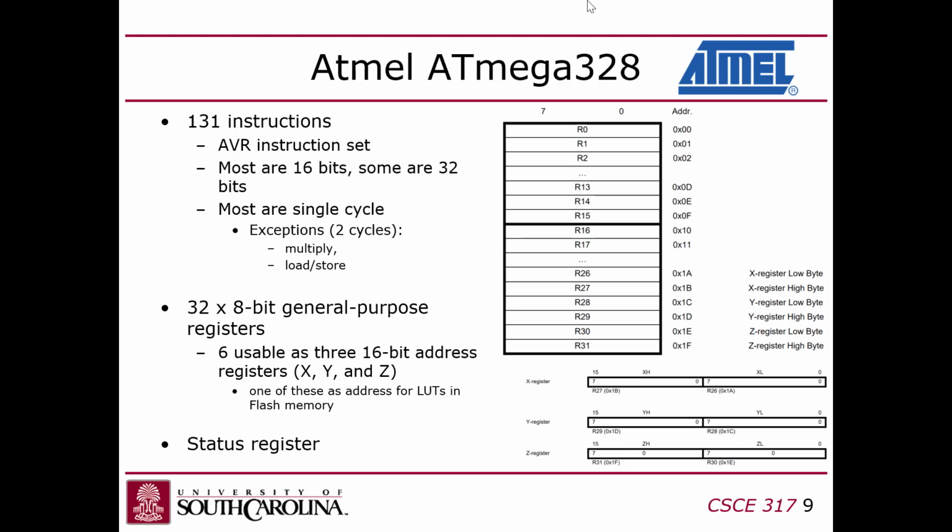Most instructions execute in a single cycle, but that's not entirely accurate because what's really happening in this architecture is you fetch an instruction in one cycle and then you execute it in the second cycle while you fetch the next instruction. So it's a 2-stage pipeline. What does that mean? Well, it means that generally speaking, it's 1 instruction per cycle unless you have a branch, and then you still get hit with the control hazard, if you remember that from 212 and in 611. So branches will still be costly.